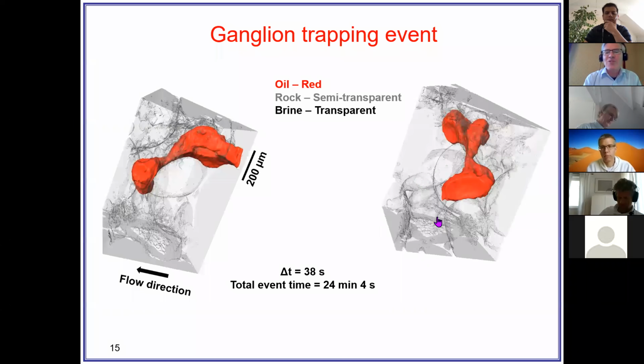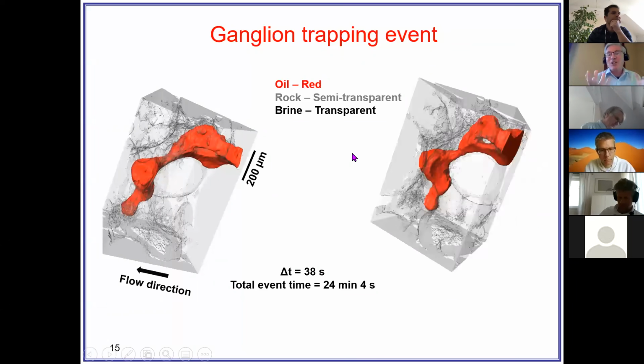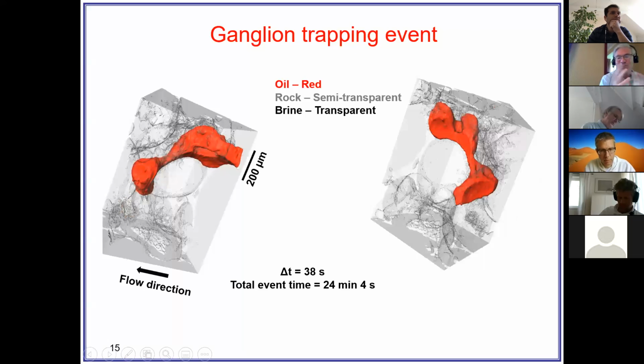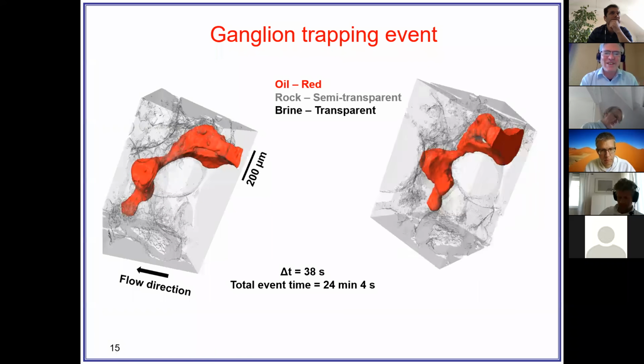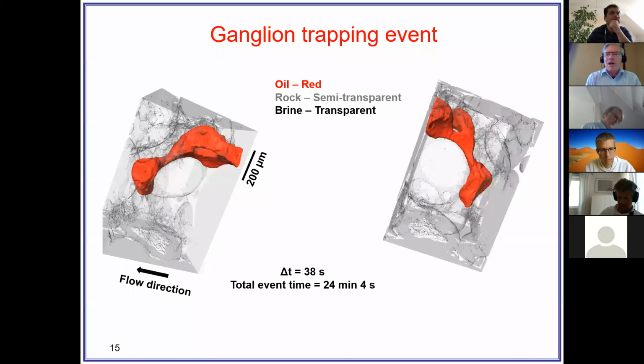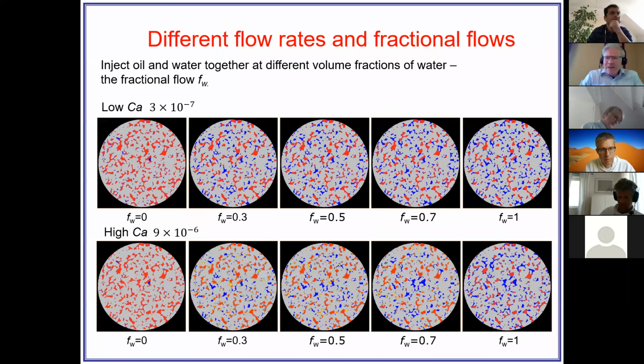Okay, the other picture on the right is just fancy image analysis, right? We're sort of rotating the view so you can see it from lots of different angles. Okay, that's fine, but that hasn't really quantified anything. Because I started with capillary pressure and relative permeability, and someone might say, yeah, okay, lovely pictures, but actually I want, in my models, this relative permeability, this capillary pressure.